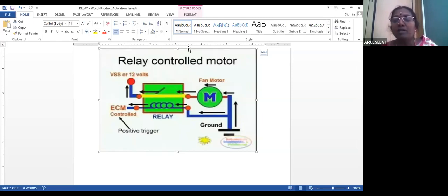It may be a motor or a bulb or any dryer or any fan motor or heater or furnace, a welding machine, electrode of a welding machine. So for any industrial application, you can assume that the load is connected in this manner only with the help of PLC, okay, through a relay. I mean to say that relays and contactors are very largely used to establish the supply to the field devices. I hope you all are following.